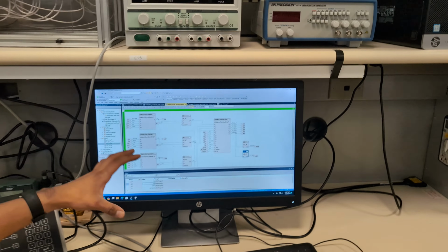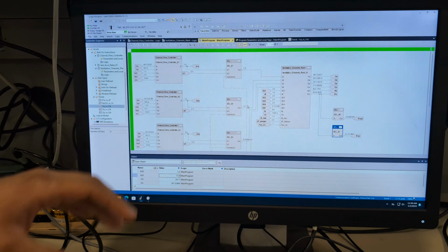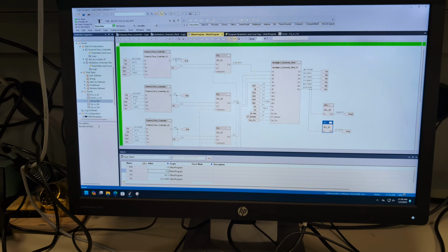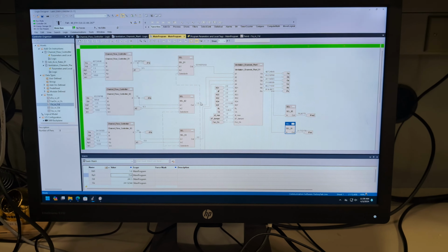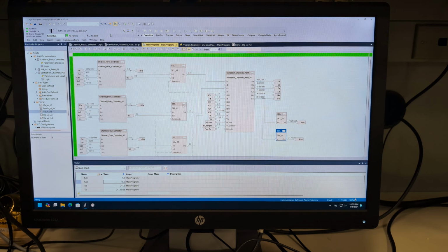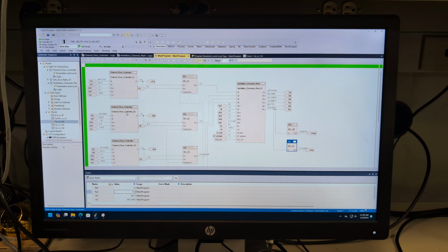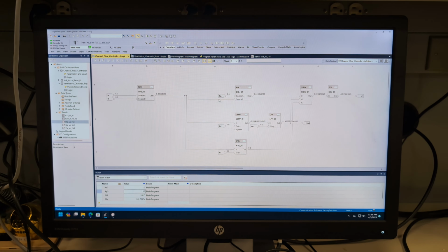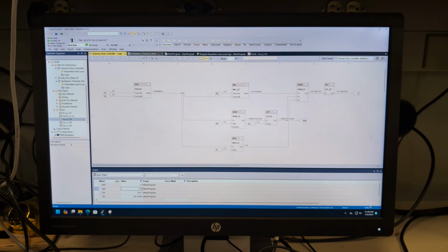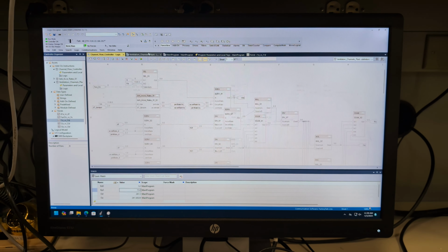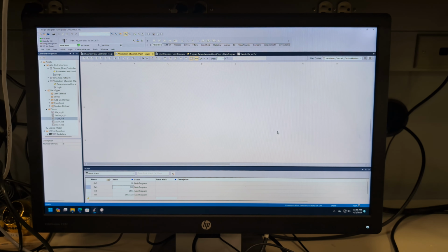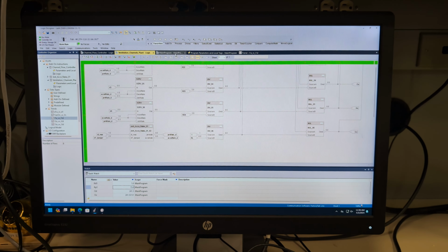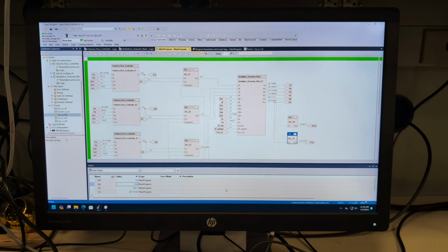We started creating a program that will control 4 different flows of air. Each one over here is a PID controller with its different KD and KP values. This is a copy of just one of the PID controllers. And then this is our plant. This is where the ventilation system occurs. And this is our whole main program over here.